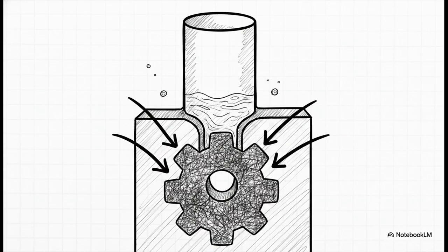You use a really clever engineering solution called the riser. Remember Chvorinov's rule from a minute ago? Well, engineers intentionally design a secondary reservoir attached to the mold, that's the riser, and they give it a significantly larger volume-to-area ratio than the main casting. Because of that specific ratio, the main casting solidifies first. As it shrinks, it actually pulls still molten metal from the riser. The riser effectively sacrifices itself, freezing last, just to backfill the shrinking casting and make sure the final product is flawless.